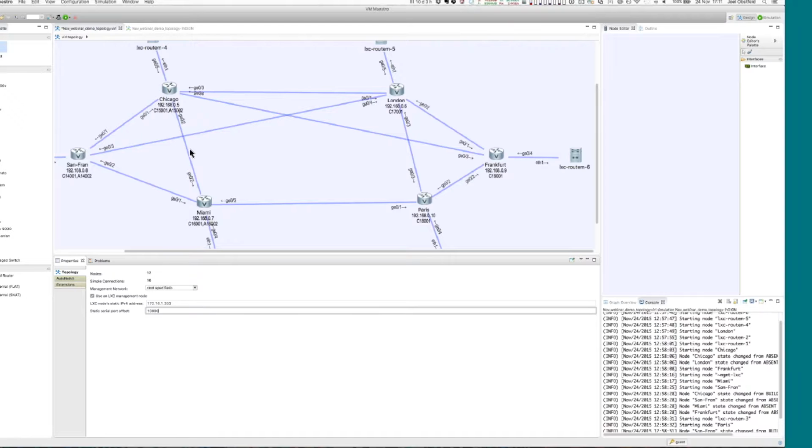And now hopefully you saw that the port number, and you can see that in the diagram here, has now shifted with an offset of 10,000. So now my port numbers are 15,001, 16,001, 18,001, etc. So that then gives us that ability to nail those ports. So every time I start up that simulation, I'm going to be getting the ports that I defined.